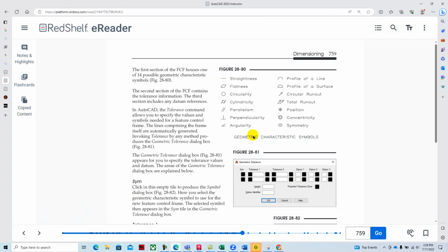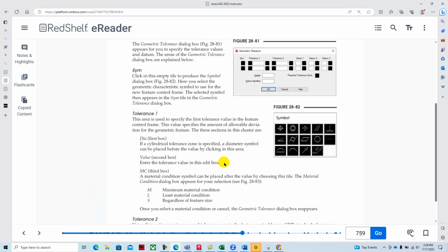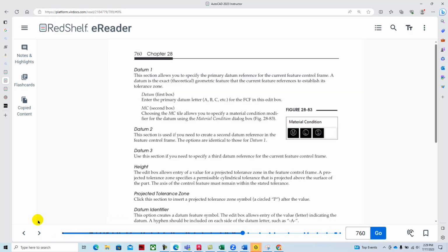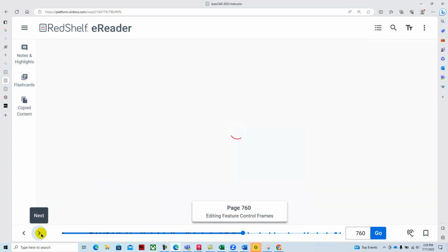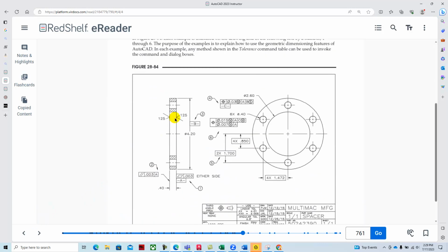There's a tolerance mark, and then you can input these different geometric dimension symbols like flatness and parallelness and perpendicularity, because as you manufacture things, certain manufactured conditions are more important, and that's a way of communicating on a blueprint things like a surface finish, or that it's got to be concentric or parallel within a certain tolerance, meaning a measurement of how parallel these are.